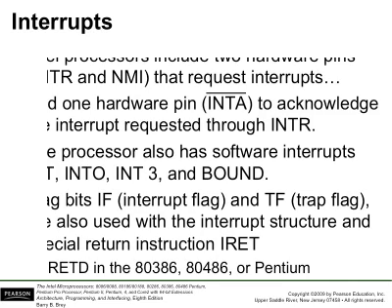There are two flag bits in the flags register that are tightly associated with interrupt processing. One is the interrupt flag, IF, and the other one is the trap flag. And there is a special instruction called IRET. This IRET must be the last instruction in the interrupt service routine so that the processor can get back to the main program after handling the interrupt.